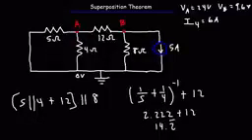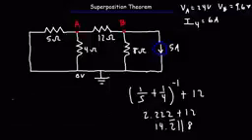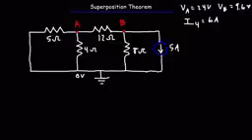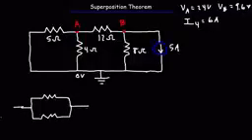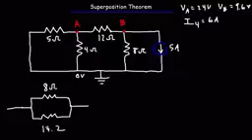Now, the 14.2 ohm resistor is parallel to the 8 ohm resistor. Well, actually, we don't need to find the equivalent resistance for that. There's no point in that. But here's what we do need to do. What we have here is a current divider circuit. One of the resistors is 8 ohms, the other resistor is 14.2 repeating.